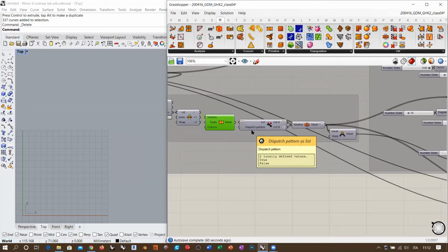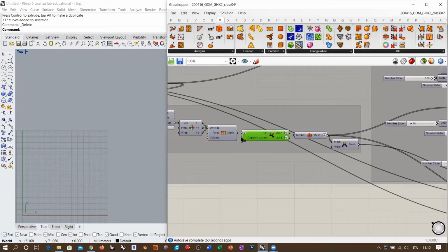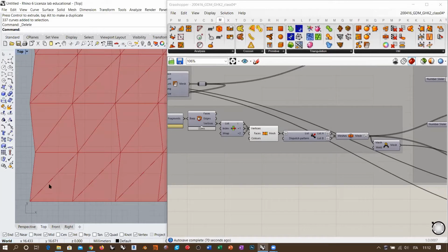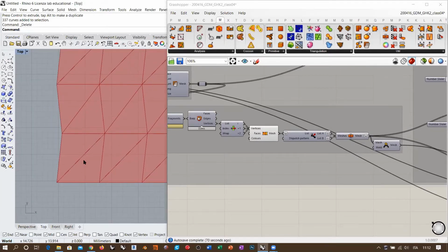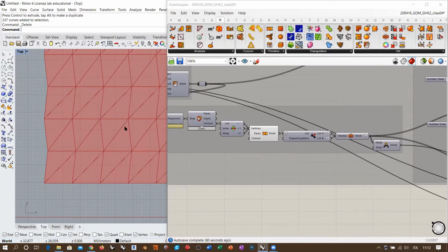and then there is, let's say, the interesting part. Okay, because it's true that we have all triangles here, but we want these triangles to fold along this diagonal. And so when we use the hinge component, the hinge component must know that this is a fold start, this is a fold end, and these are the two tips. And this for all the triangles in our mesh.